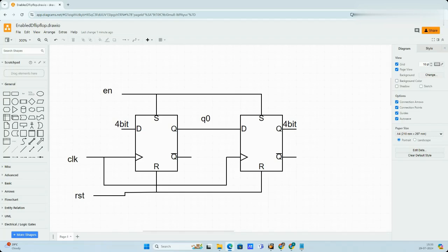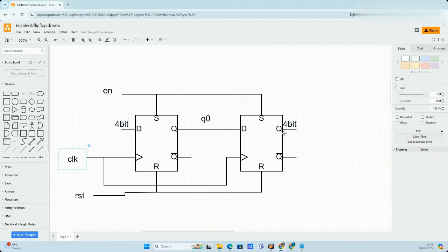So what the synchronizer shown in this figure is, is a device that receives an asynchronous input D, also a clock, and produces output Q within a bounded amount of time. So the output has a valid logic level with extremely high probability. So this is the reason we are using a synchronizer here.